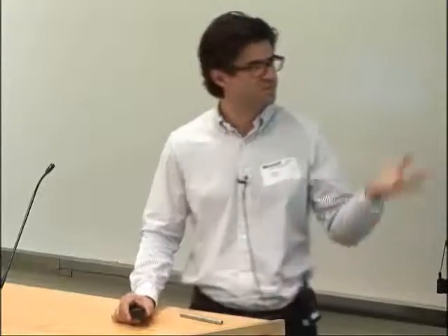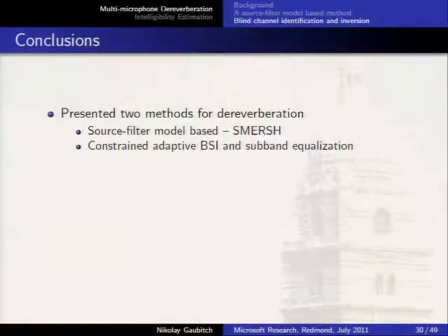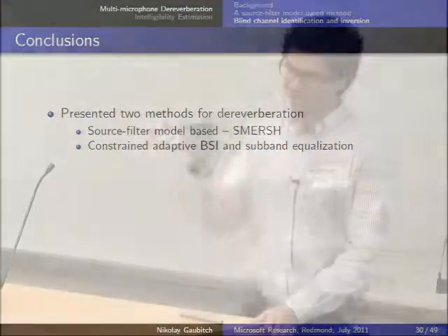This was one part of my PhD work, and one of the conclusions I got to is that I think this is nice because it gives you hope that at some point you might be able to actually do perfect dereverberation. It's there in a very artificial scenario, but at the moment, the way things work, it's not really possible because you need to be able to track the impulse response within seconds, less than seconds.